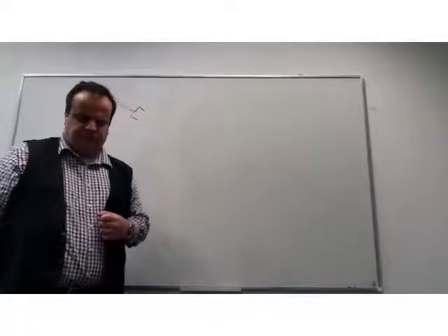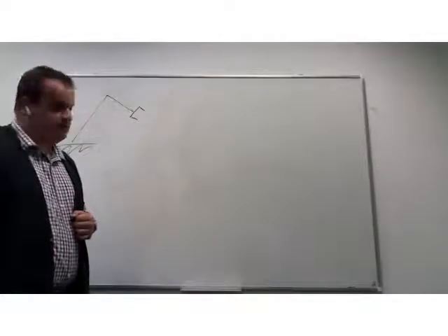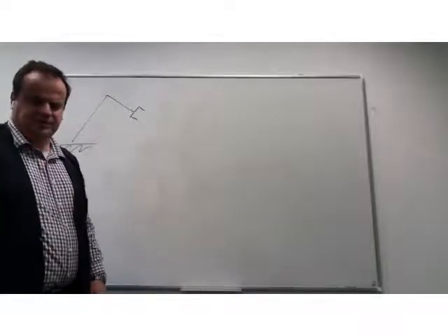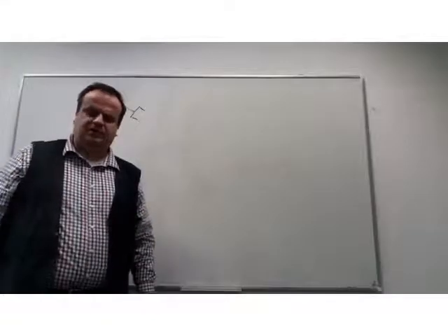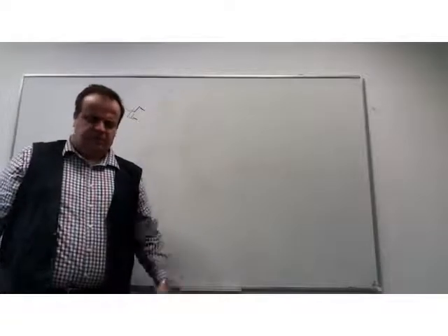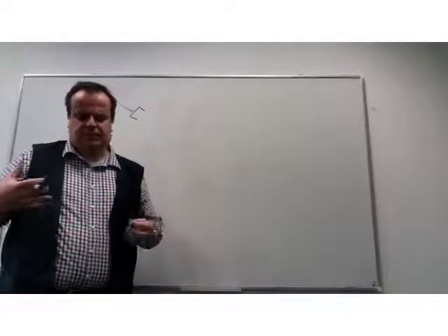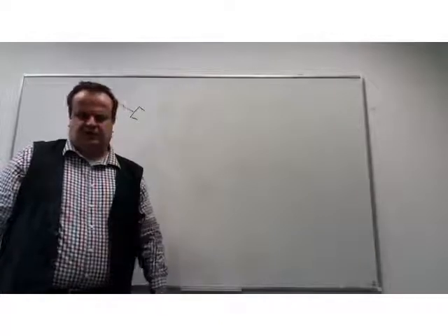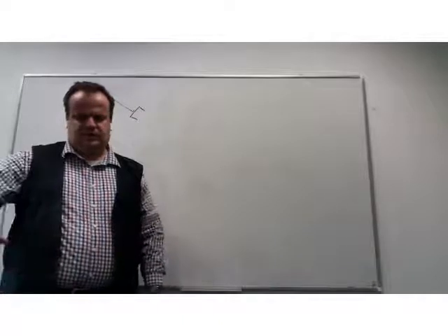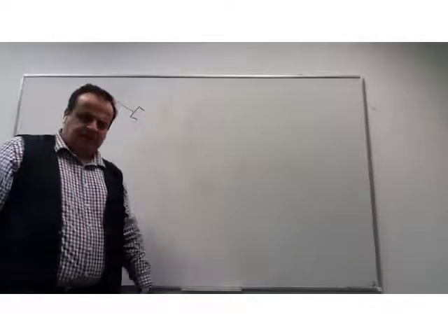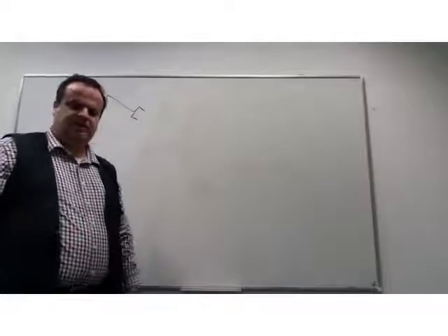manipulator, usually a 2D robot for the whiteboard. In the general case, of course, it's a 3D structure in the world. What we discuss here applies to mobile robots as well, but we are using manipulators as examples because they usually have more degrees of freedom than a regular mobile robot. A mobile robot has maybe 3 degrees of freedom, 2 translation, 1 rotation. The manipulator has, in the general case, 6 degrees of freedom. So we have a lot more parameters to deal with.